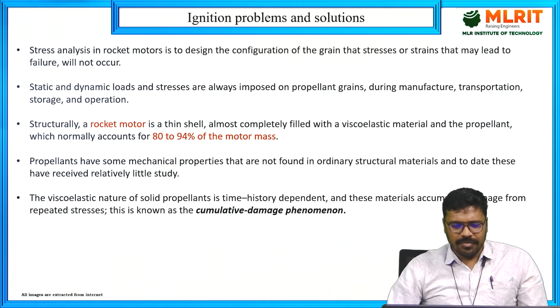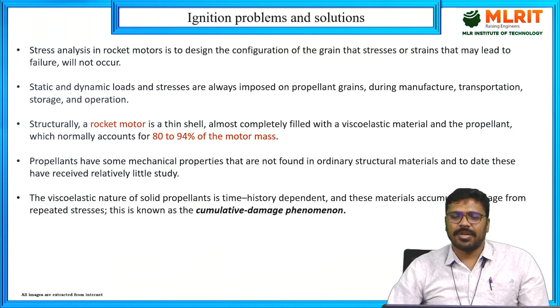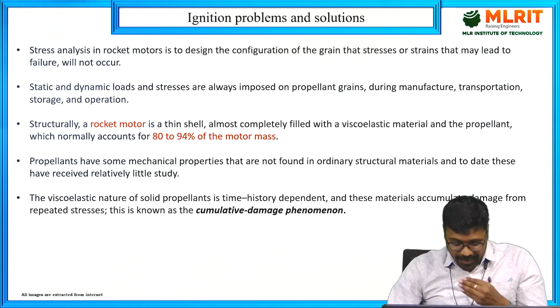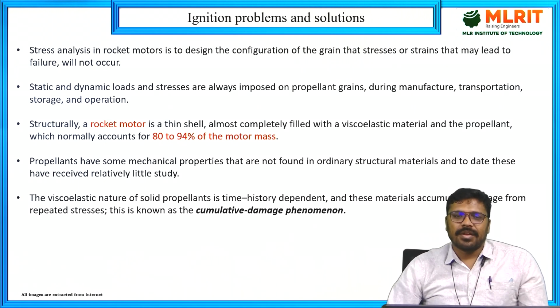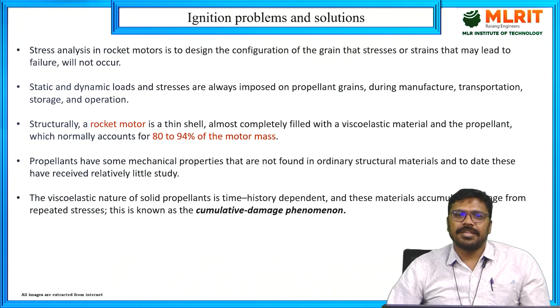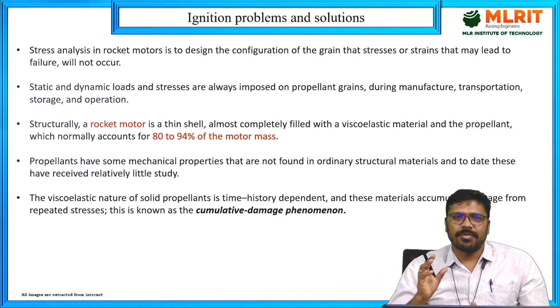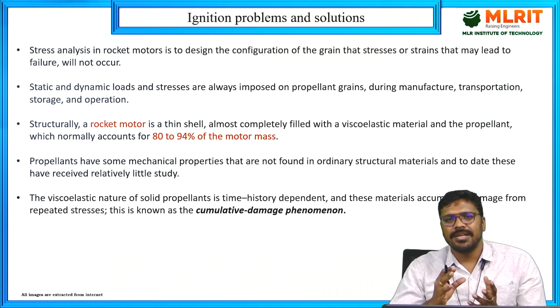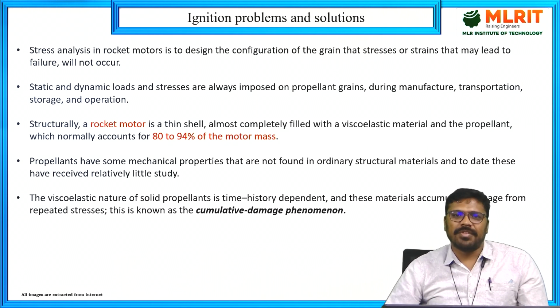Okay, we have gone through the loading strategies of propellant grains, right? There are two types of loading strategies: one is cartridge based, and the other is freestanding. We make the propellant grain by a casting process. We place the powder of the propellant grain, mix it with the binders, and make the powder into a solid form of the propellant grain.